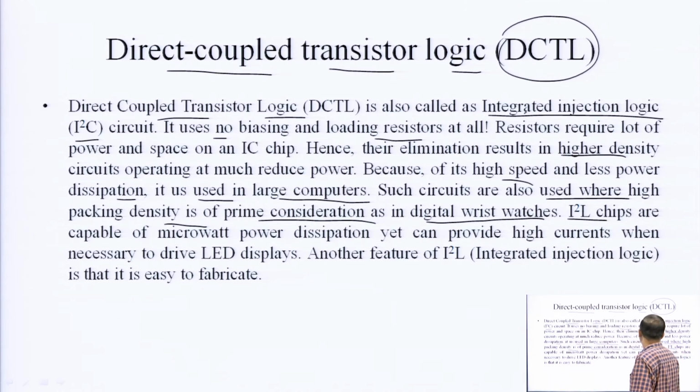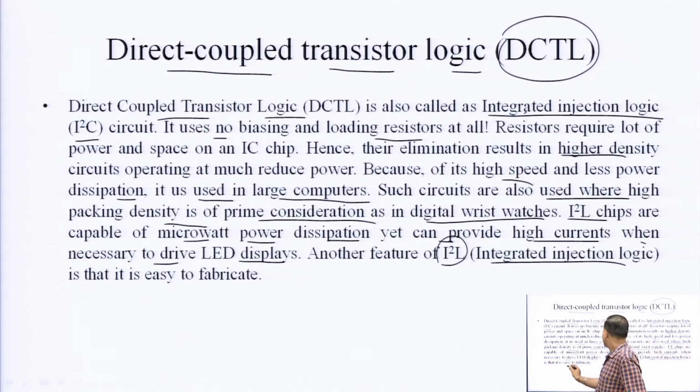I2L chips are capable of microwatt power dissipation, yet can provide high currents when necessary to drive LED displays. I2L means integrated injection logic, and here we can say integrated injection logic, I squared L, both are the same. It is also very easy to fabricate.